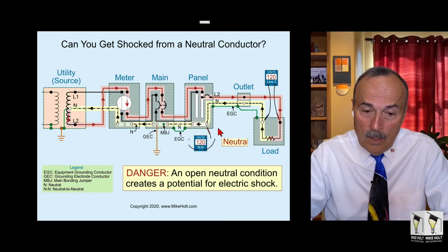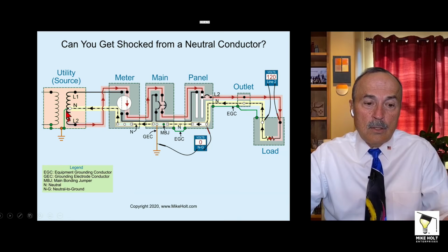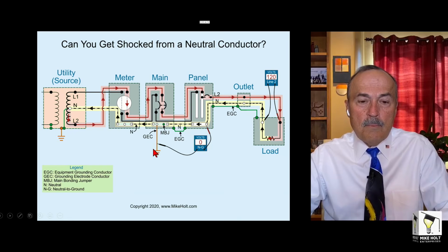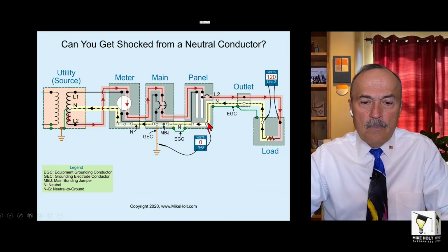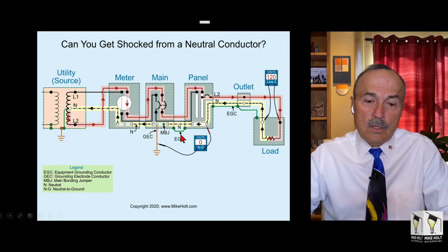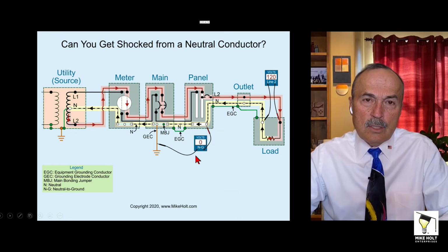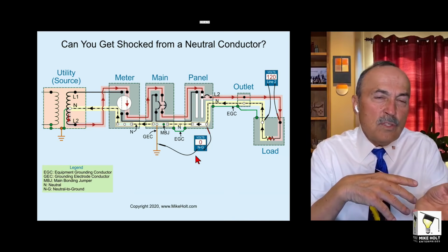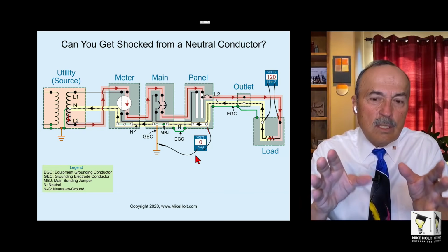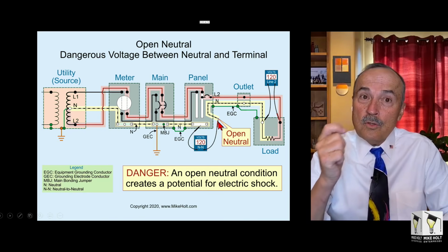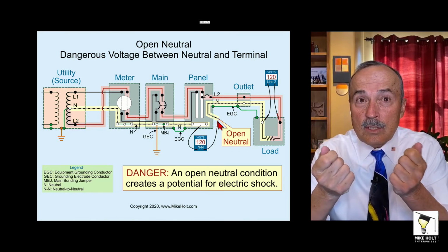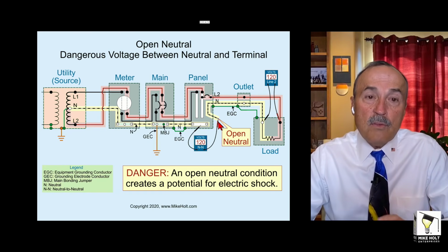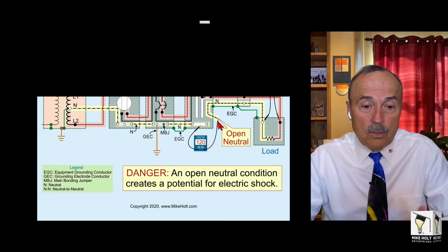So can you get hurt by neutral? Well, if the neutral is complete and the neutral is grounded at the utility service or the separately derived system, and you're grounding it at the service equipment, not that that really makes a difference anyhow, if you touch a neutral and you touch the earth, it should go to the earth, not through you. Technically you're going to measure some voltage, but I didn't give you the amount of current. You don't know what the NEV voltage is, so we're just going to say it's 0 volts. But if you open a neutral and you get in series with a neutral, now you're talking about a series circuit. You're going to be very, very close to 120 volts, and many people have gotten killed by that scenario. I've been involved in a few cases with that. I hope that answers the question on the neutral.